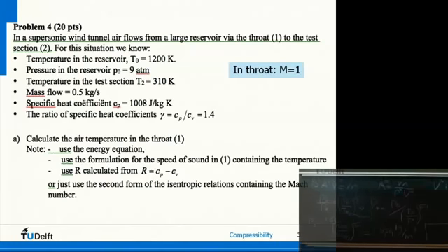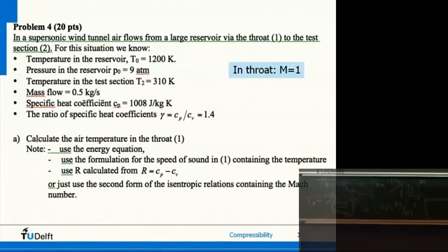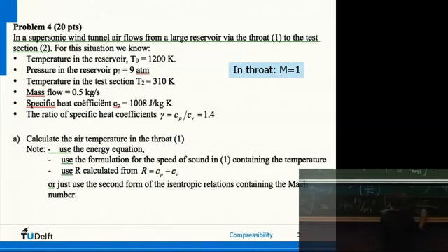Almost, because the question was the area in the throat. Mass flow we had, speed we had in the throat. Now we know the density in the throat, so now we can find the area through a very simple relation. So A star is equal to m dot over rho star V star, so that was a half. Rho I just computed, 1.674.